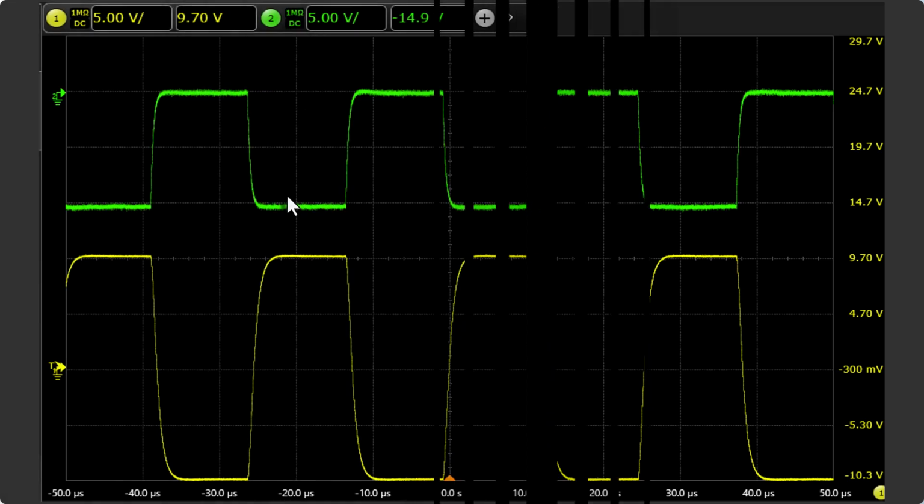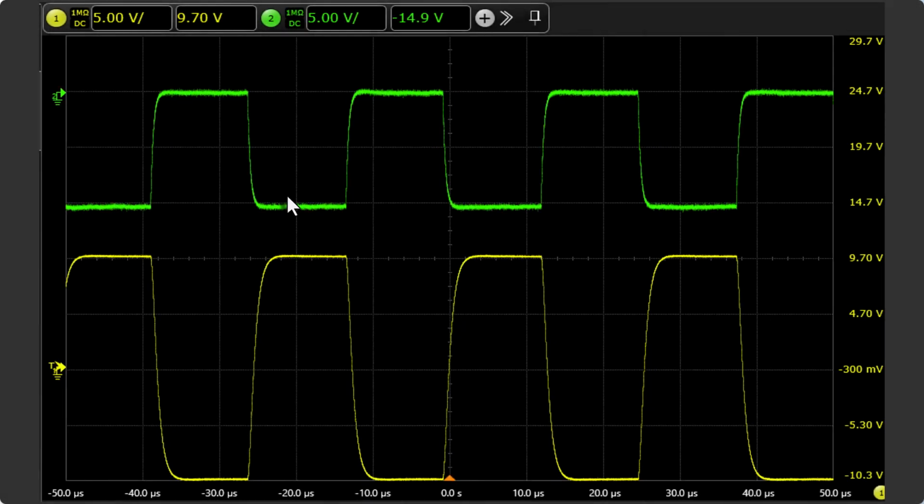And then, of course, when the output of the buffer amp is negative 10 volts, or the DAC is at maximum value, we're going to get that value doubled because we have a gain of 2, so it's going to be negative 20 plus the 10 volt reference, that's negative 10, and of course it's inverted for a positive 10 volts. And then, of course, all the values in between fill in all these different voltage levels.